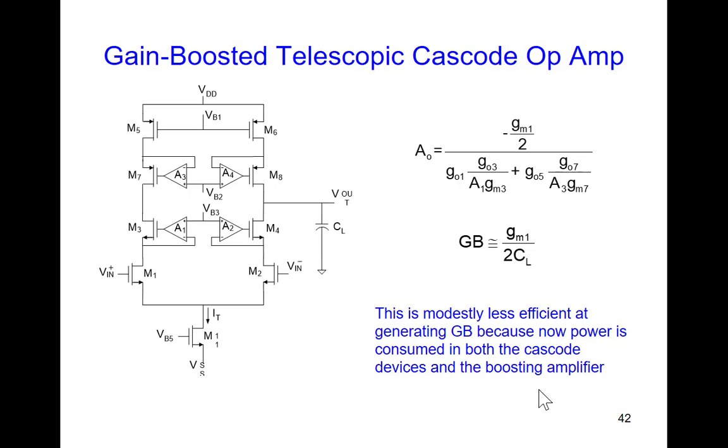Why don't you think we use more complicated structures for the A amplifier? It's very complicated. Yeah, it's probably a good point. We don't want to burn any more power than we have to in that A amplifier. We want a reasonably good frequency response. You're going to find that this A amplifier here, we're going to have a hard time beating that very much. The first one we started with, the simple one, we're going to have a hard time beating from a power efficiency viewpoint.